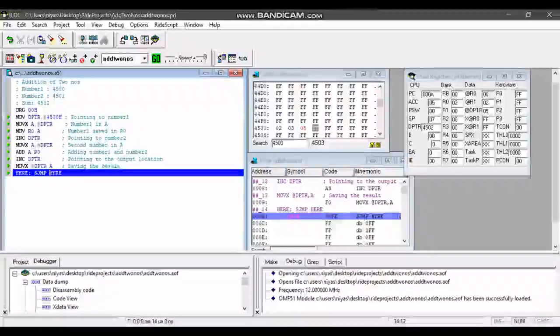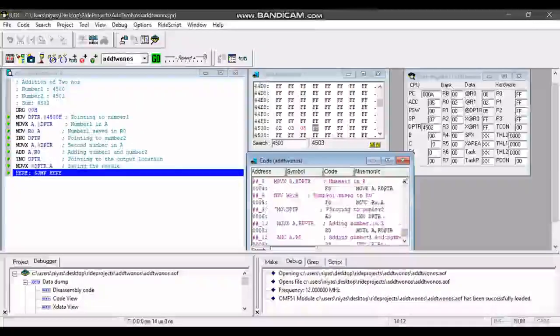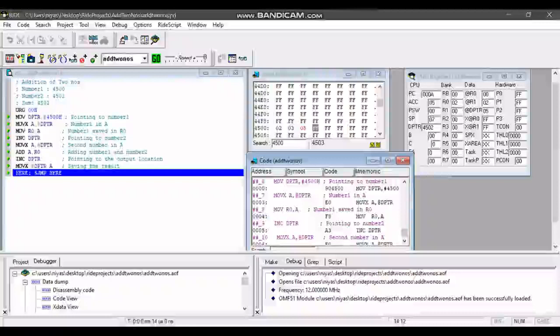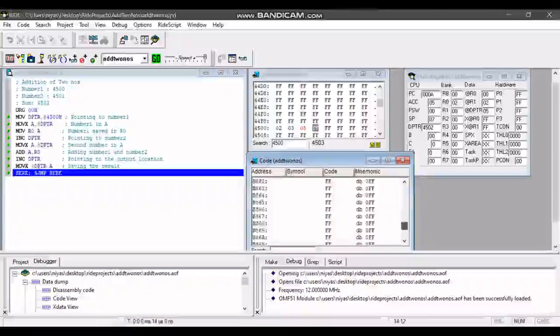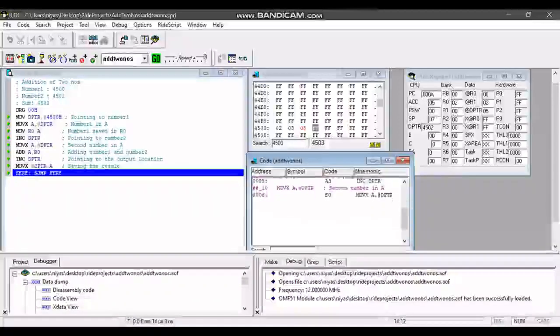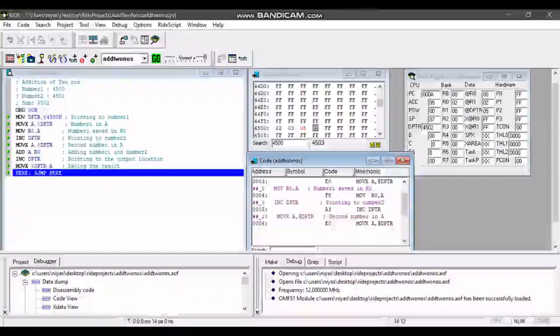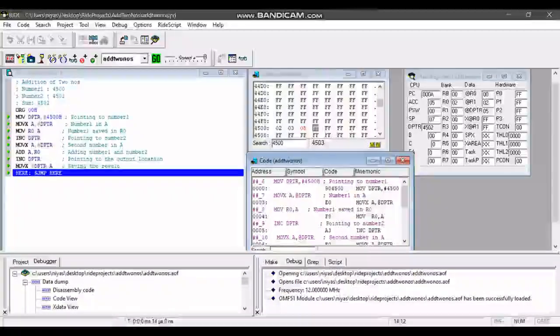We have written 00H, that is why the program memory started saving from the 0000 location onwards. This is 16 bits. The address of the next instruction to be executed will be coming in the program counter. If you see, the next value of the program counter is 0008.